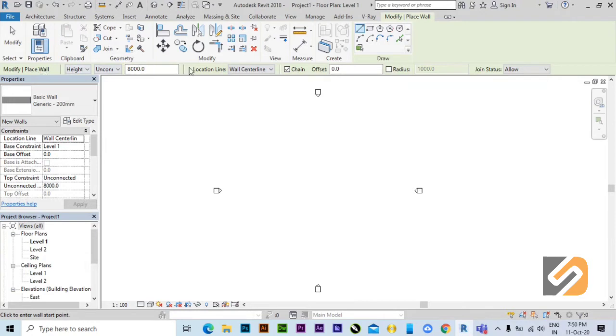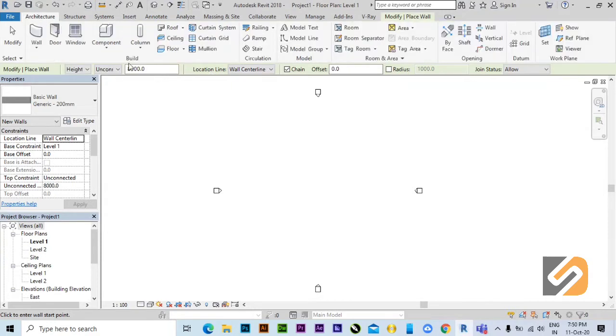So the options bar is similar to the command line in AutoCAD. It will let you choose how you are going to place the wall into your project. And for all the tools there will be options. Yes, we are drawing in 3D directly. We are now in level one, and you are drawing 3D and 2D together, because once you view from the top view, you are seeing the 2D, but you can switch to the 3D view directly.